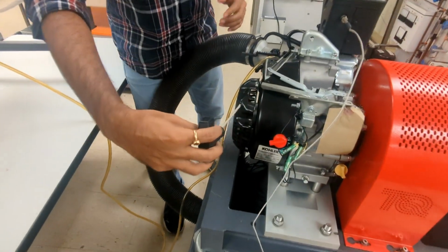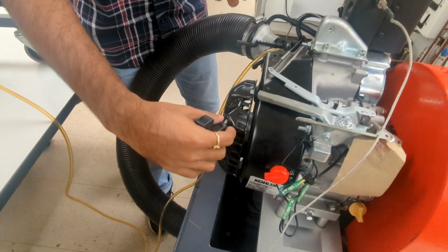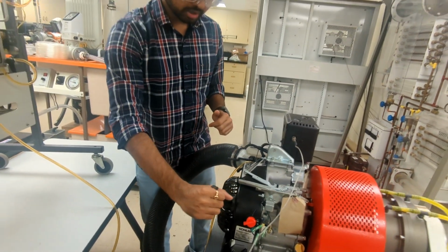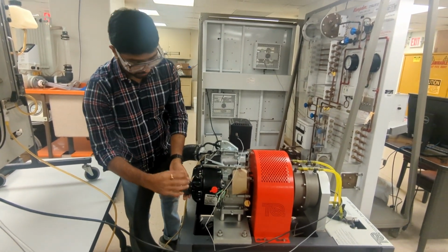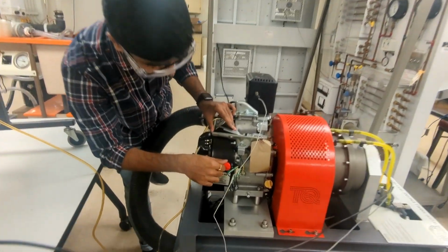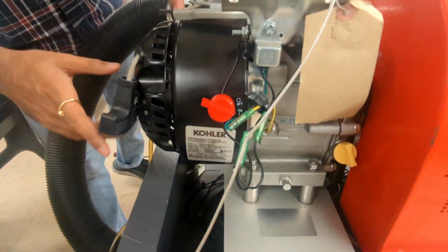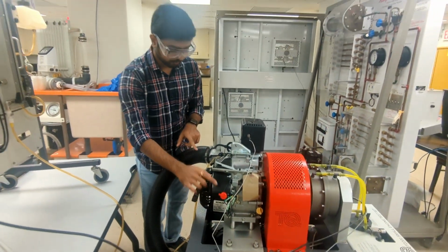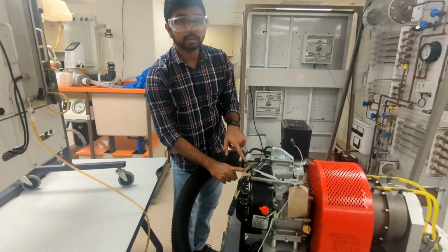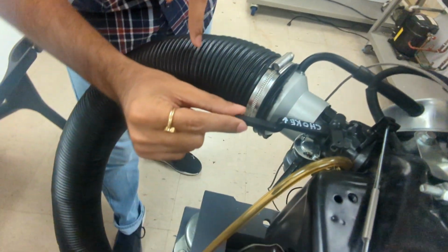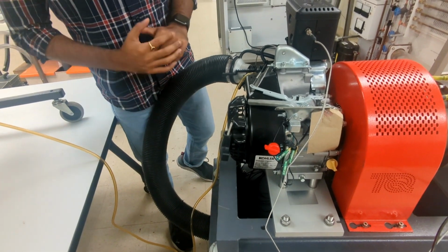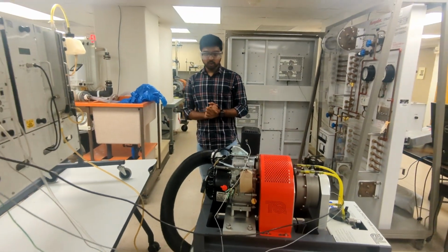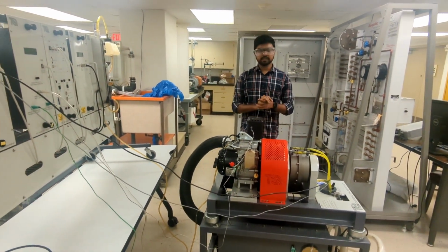I have this lever over here. It's a kind of manual mechanism. There is no power switch to run the engine, so please make sure you pull this string harder to run the engine. Also make sure this is on, otherwise your engine will not start. Again, I will repeat, this fuel supply line should be on. Make sure this is on. This choke valve is in this position. Once everything is done, then use this string to pull it harder to run the engine. That will help you to start the engine.